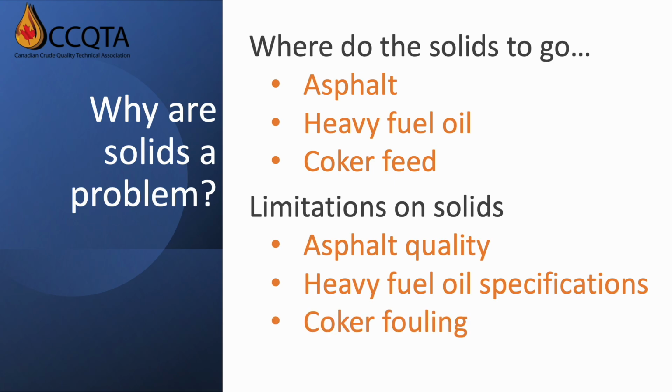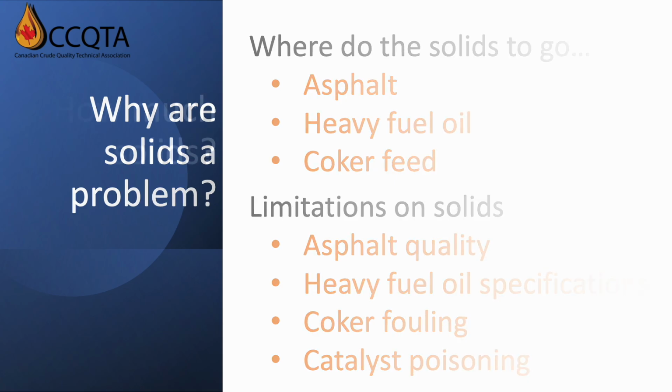And coker heater fouling and flash drum foaming have been reported, and those producing anode coke are very concerned about solids contamination. Some of these smaller crude solids will also be present in distilled fractions. Here the concern becomes exchanger and heater fouling and catalyst poisoning in hydrotreaters, hydrocrackers, and fluid catalytic cracking units.